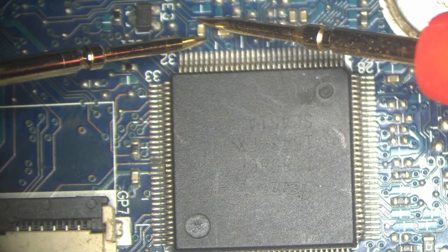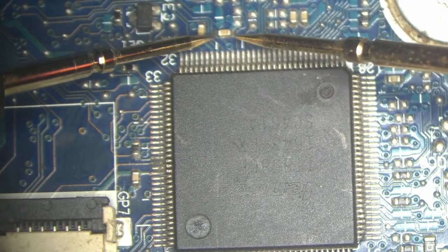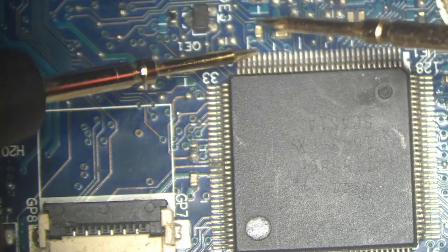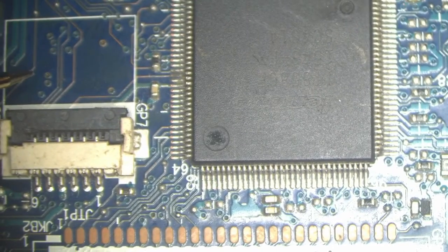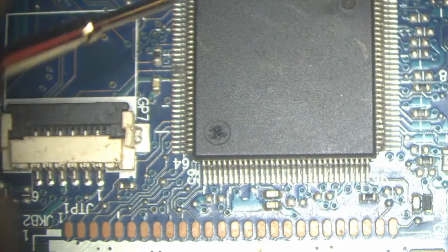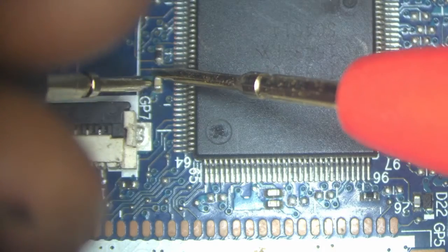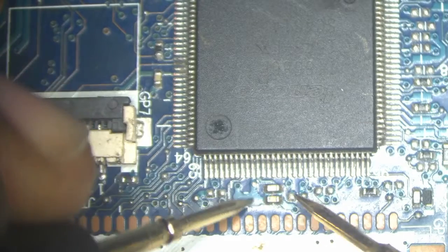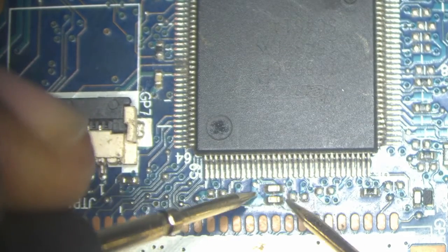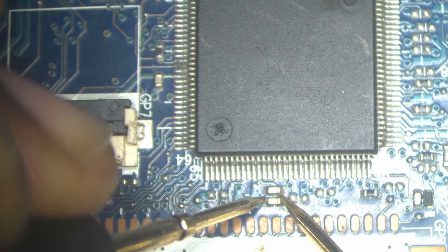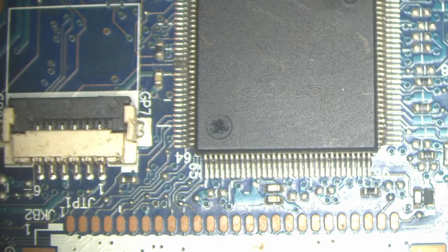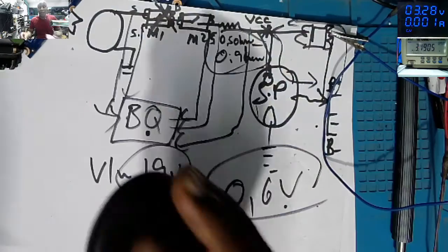Check this capacitor: zero. And here, this one is shorted. Here we have more capacitors: zero. You see, those capacitors here are shorted. We have a problem there.